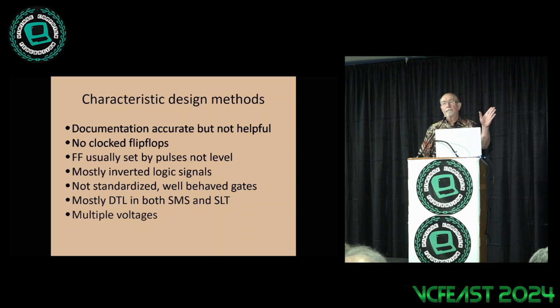So in SLT, IBM has multiple families of different speeds: slow, medium, and fast. They all have their own logic 1 and 0 levels, their own voltage rails. And then to make it even worse, IBM has chosen to leverage, good business sense, older technology that they've designed inside the new one. So when you look at a 360, some of the cards in there are SMS from the 1950s. The power supplies are all leveraged things they built in the 1950s.